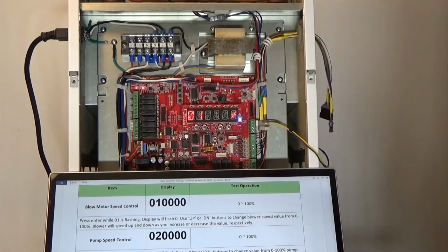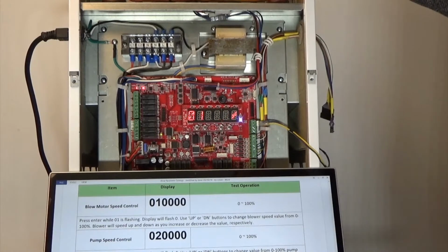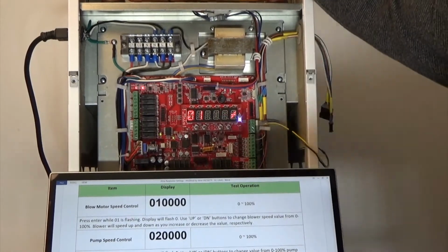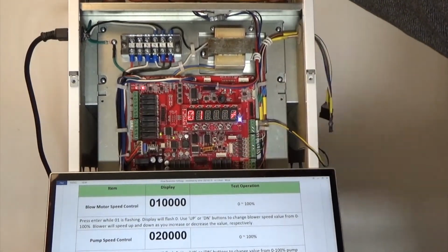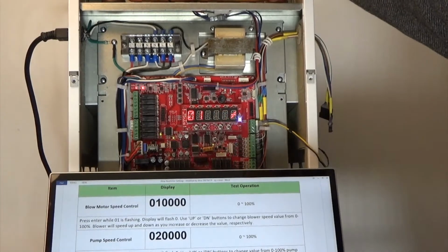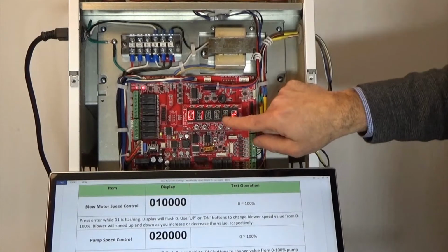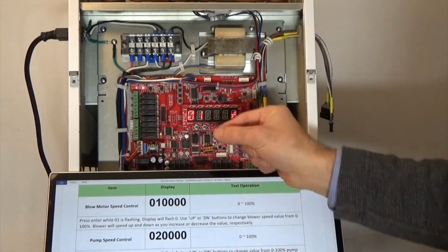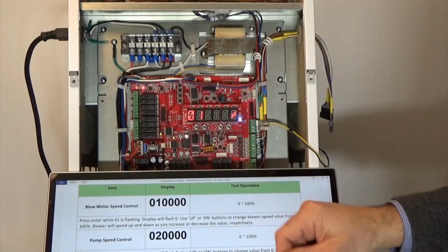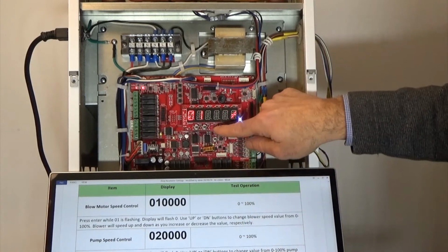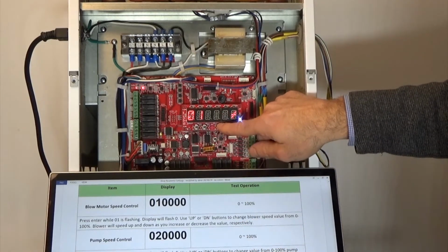And then once we know what the maximum CFM rate that we need is, for example, where we're getting good volume at all the registers, not very quiet, kind of a perfect scenario, then we can go into our settable controller or settable parameters, into our heating and cooling parameters, and adjust those accordingly.